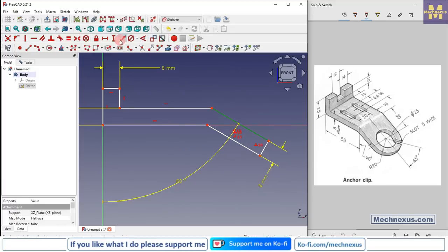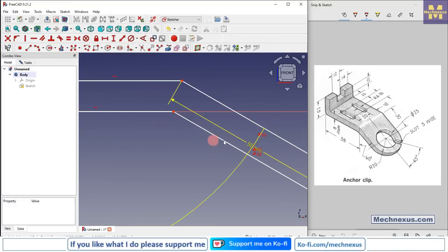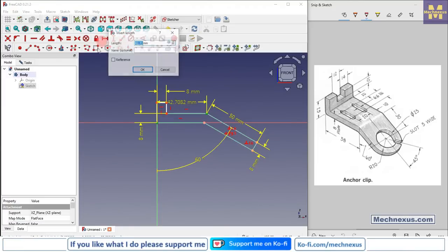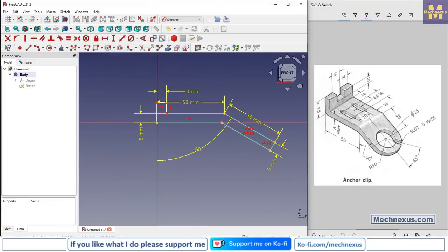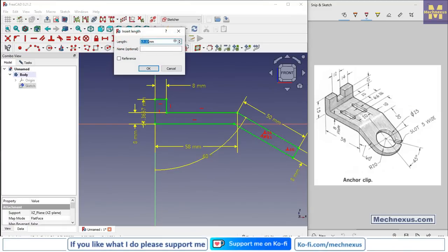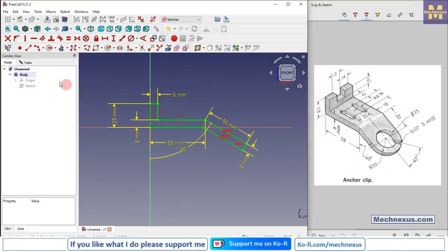Select this line and add the dimension of 50. Let's move it, and from this point to this point is 58. Move it and select this line and add a vertical of 25. So we have a fully constrained sketch. We will come out of the sketch. So here is an exit sketch option.